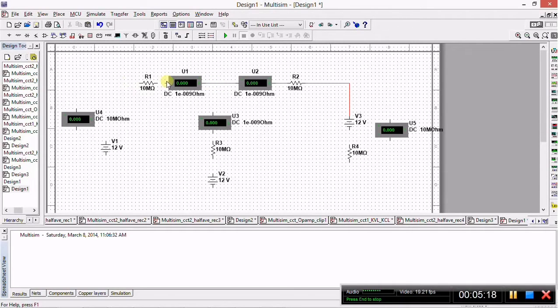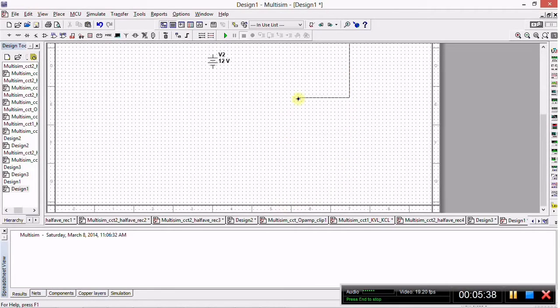In case you forgot from last video, I'm also missing a really important part of the circuit, and I need to place it after I've connected all these components. Remember, in Multisim, circuits do not simulate without a ground, but luckily Multisim will give you a warning if you attempt to simulate without inserting a reference point into your circuit.